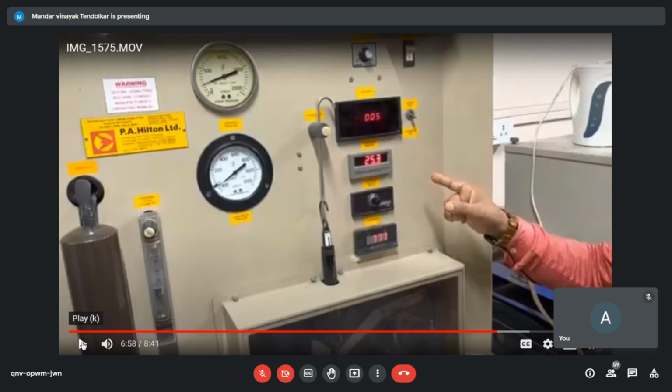So let's say 27 compressor inlet, 30 compressor outlet, which is condenser inlet. Naturally, after the water circulation, heat rejection, 30 comes back to 27. That is condenser exit, and condenser exit is your throttle inlet. So that is 27, and throttle exit is even further lower temperature, that is 25. Then it will absorb the heat from the evaporator, from 25 again back to 27. So this is how the cycle completes. 27 to 30, 30 to 27, 27 to 25, and again 25 to 27. Fine.